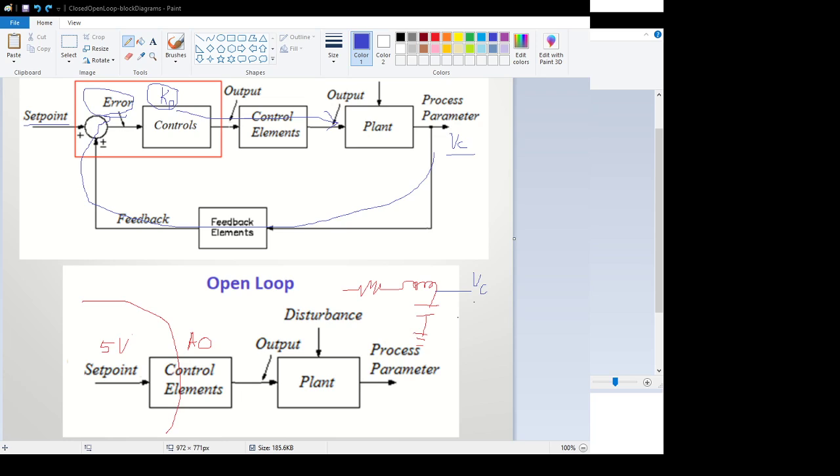And then when we send it out, it's going to go out as an integer. So when we send it out, it's going to go out as millivolts. The control out is actually in volts for this example, and then we multiply it by 1,000 to get millivolts, so we can actually send it out channel 0 of the analog card output.